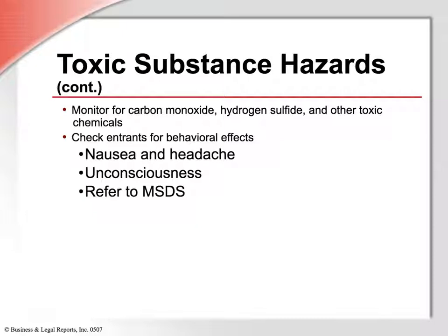Continuing on toxic substances, you should monitor for carbon monoxide, hydrogen sulfide, and other toxic chemicals. Check the entrant for behavioral effects like nausea, headaches, and unconsciousness. Refer to the MSDS for specific behavioral effects of exposures to other toxic substances that might be present also.